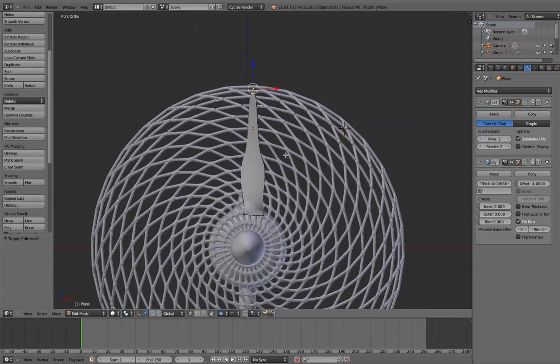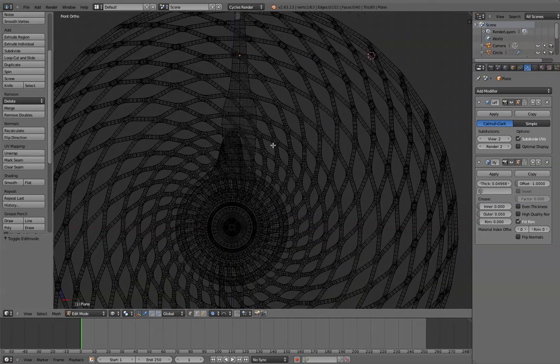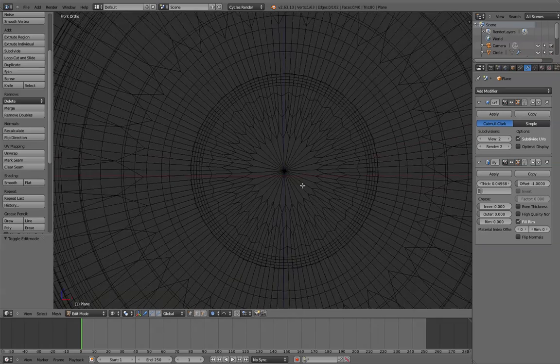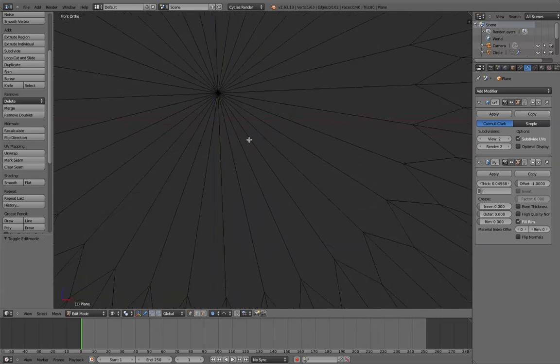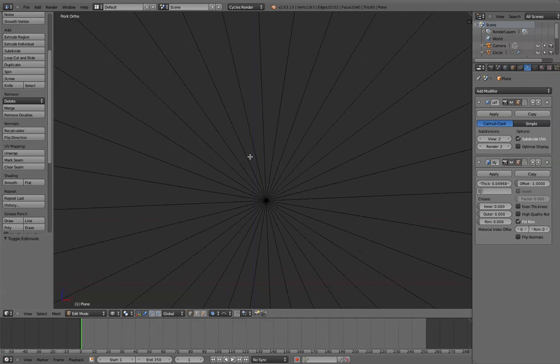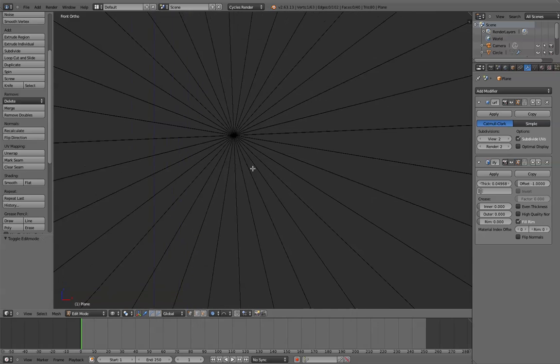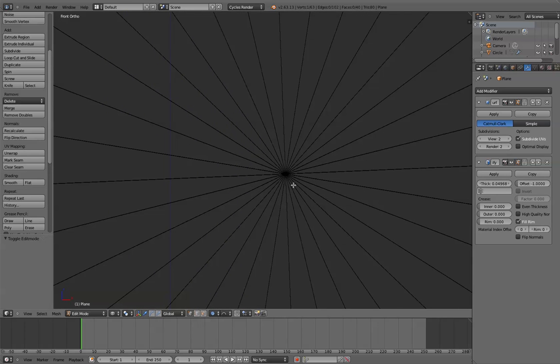First, what I'm going to do is tab in Z. I'm just going to go and try and get the very center point of our assembly here. And if my modeling had been a bit cleaner, that would have been the center point of the scene, and I could just align my cursor to center. But no one's perfect, are they?